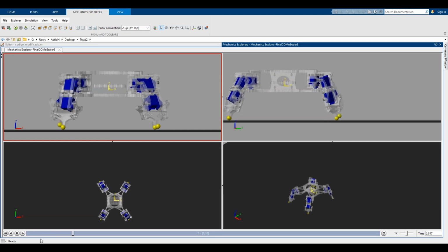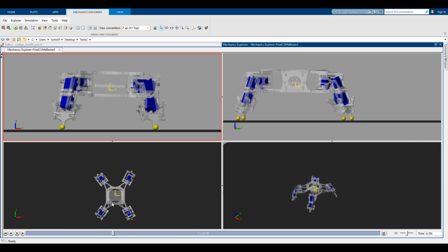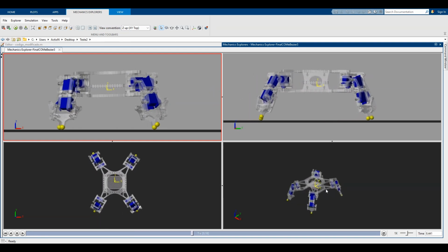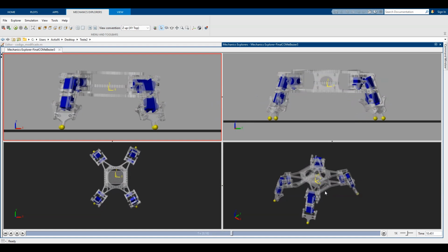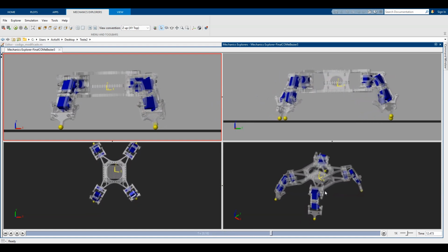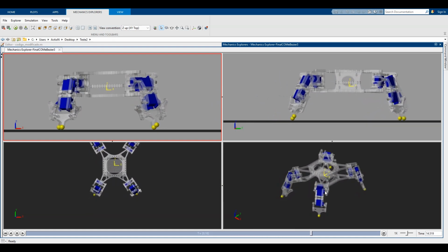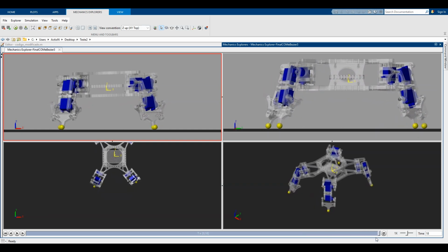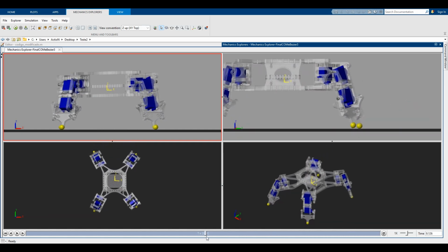The slow and deliberate leg transitions allow for better weight distribution and a wider support polygon at all times, minimizing the risk of tipping or instability. This gait is especially suitable for low-speed navigation in uneven terrains or when the robot must maintain balance in response to external disturbances.